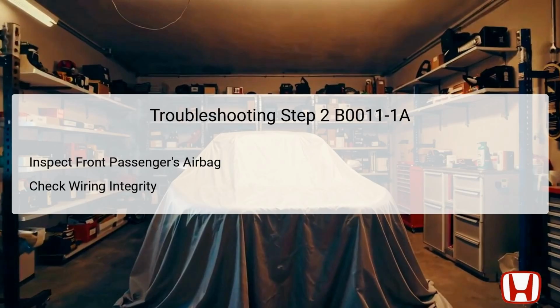The goal is to test the inflator circuit's integrity and ensure it can handle the specified resistance, which should be around 2 ohms. Observe if DTC B0011-1A reappears after performing the confirmation procedure. If the DTC does not return, it indicates the problem may lie within the airbag itself rather than the wiring. Should the code persist, further investigation of the wiring and the SRS unit will be necessary.